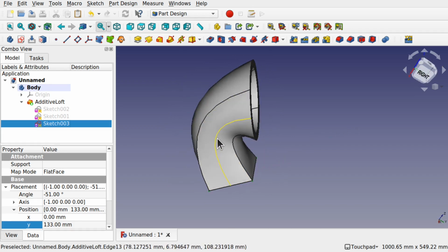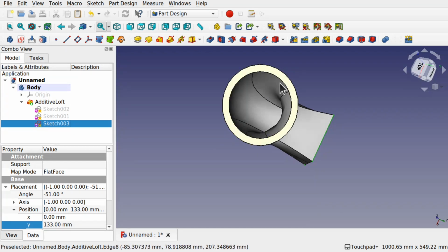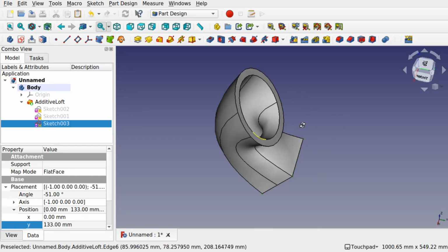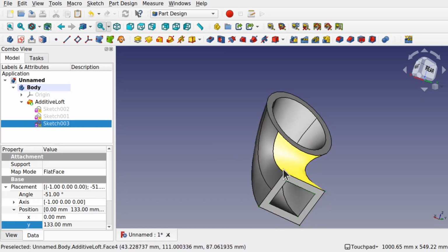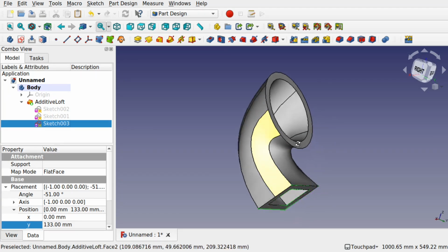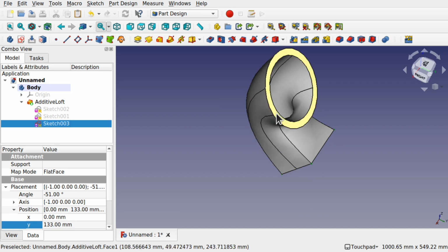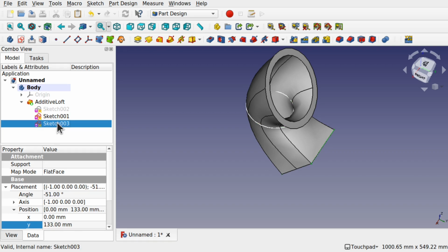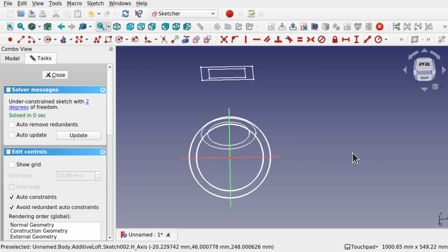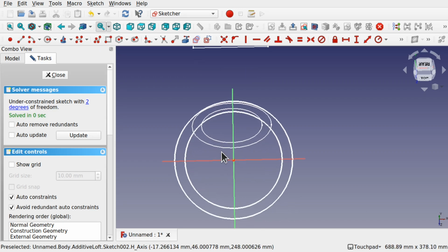We've got an additional edge which is part of the circle, and that comes from the vertex of the circle. So if we look along here, what we should have with the square, these edges come up and attach, and then we look at the circle here, you can see we've got this point here, and if we come up to the top circle, if we can find it, all we need to do is split this into 4. So rather than having one edge, we match it with the other profiles. You don't have to do it, but it is recommended to get a better shape.